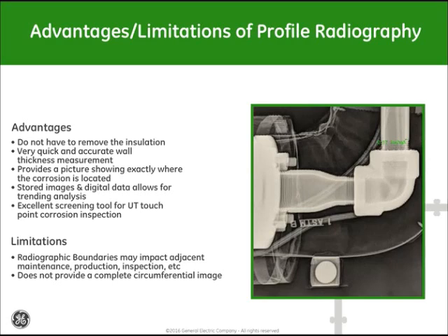But again, we don't have to remove the insulation. We can do a very quick and accurate assessment to understand wall thickness. We can store that data and trend it for future maintenance evaluation. And it becomes a screening tool for additional technologies such as ultrasonics, which Dave Jankowski is now going to take you through. So thank you for your time.